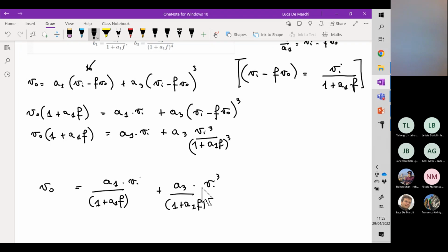But if we look at the signal-to-noise ratio at the output, we have the same relationship between noise and the signal component, because the signal is amplified by a factor equal to the gain of the amplifier, and the noise as well is multiplied by the same effect. So there is no benefit in the amplification of the signal in this case.